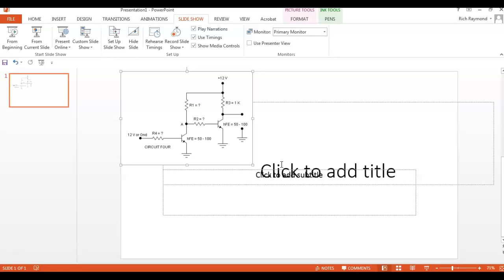Your power amplifiers usually work in it, and we go through stages. So how many volts do you think you're getting off that little antenna you have in your car or on your cell phone? None. So you know we got to go through a lot of different gains, right? We start off with low gains, and we'll talk about it later, and we end up with real high gains on the end. About 6 stages of amplification is usually what we go through to get it from almost nothing to something we can use.